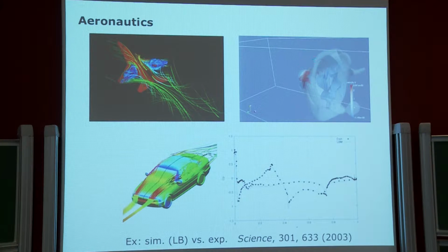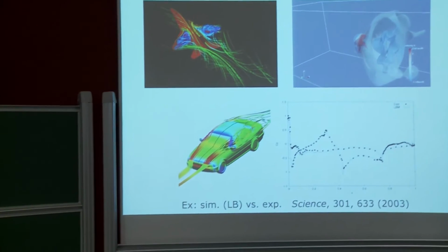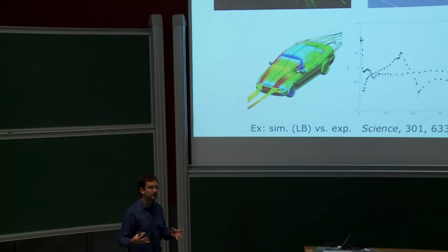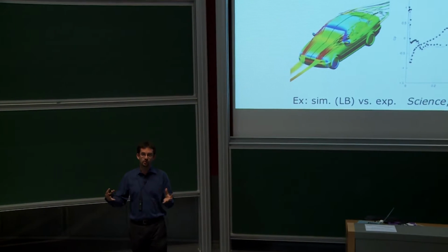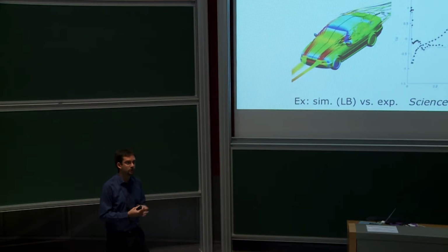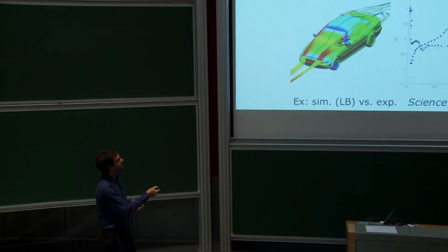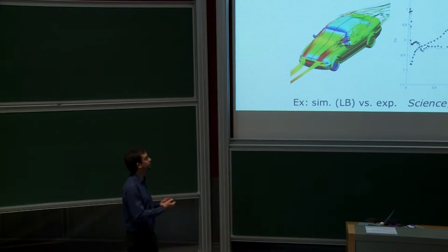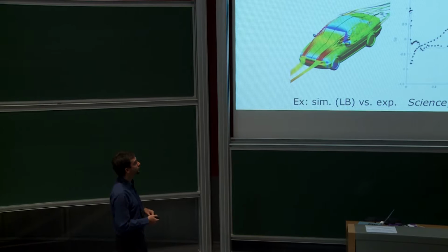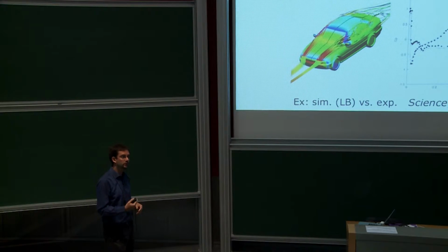And for example, if you're designing a boat, it's very important to know what the flow around the propeller will look like, because if the velocity is too high, then the pressure will drop below zero. You can have negative pressure. You will nucleate bubbles in water. That's called cavitation. And then when the bubble collapses, it will generate shock waves that may damage the propeller itself. So that's very important also in this context to have a good description of the flow around the object you're interested in.